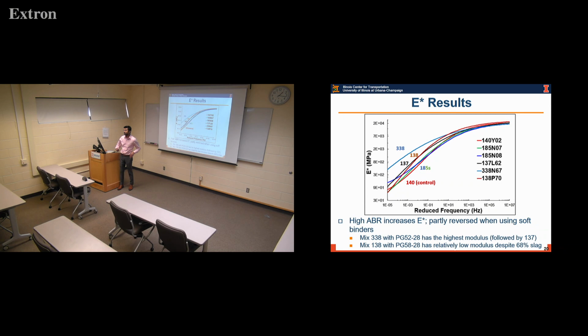So it depends on what test you're talking about here. Let's suppose IFIT. So for IFIT, what we try to do, first of all, is apply correction factors, like the air void correction factor. Because over time there's compaction happening, and the field cores extracted, let's say, during 2017 compared to those of 2015, will have a lower air void. So we try to use the correction factors which were developed for IFIT.